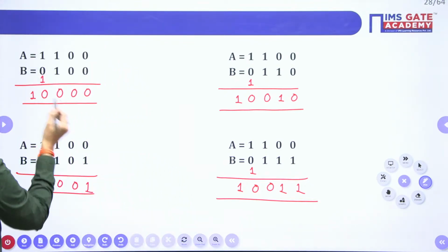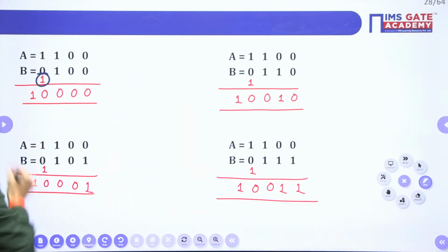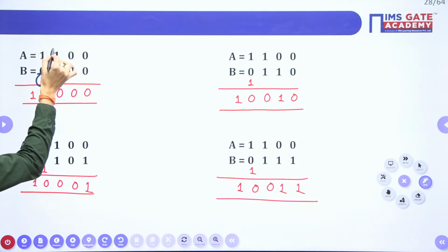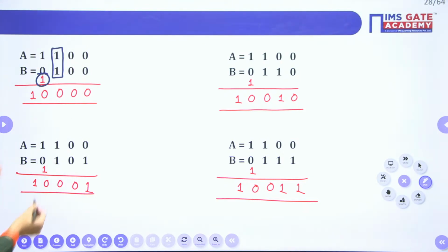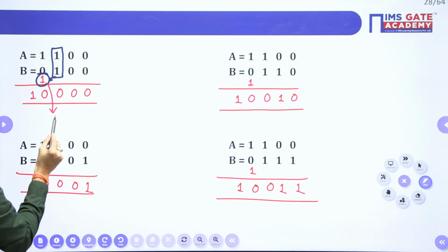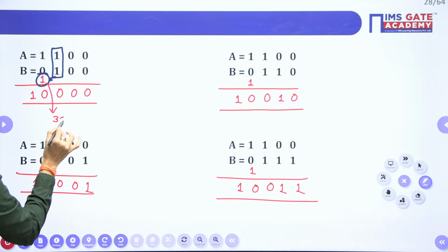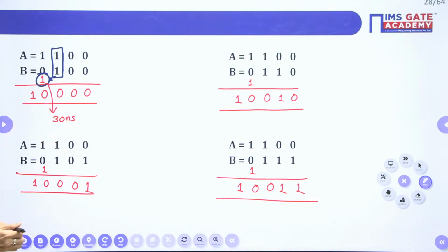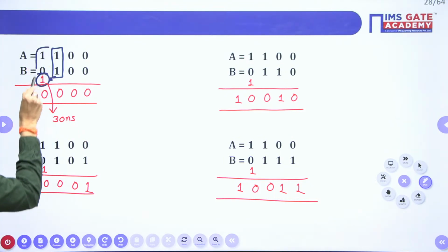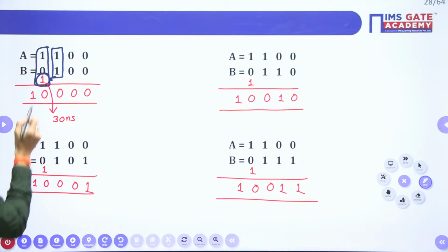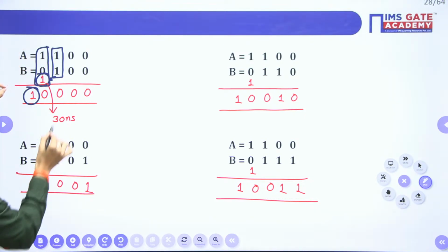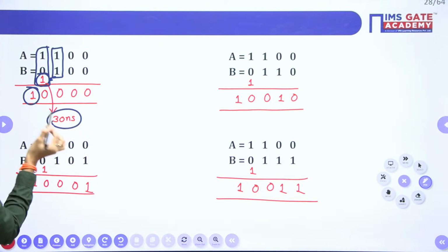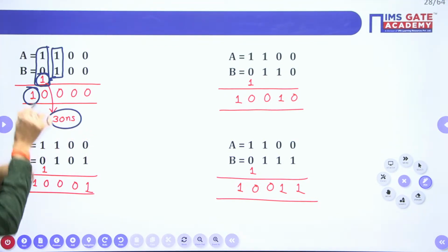See here you are getting the carry output by the third stage full adder. That particular full adder is producing carry output as 1 at what instant? At 30 nanoseconds, this carry output is 1. Now this fourth stage full adder is also producing carry as 1. But this one you are getting at 30 nanoseconds. That means this particular delay we have to consider, right?